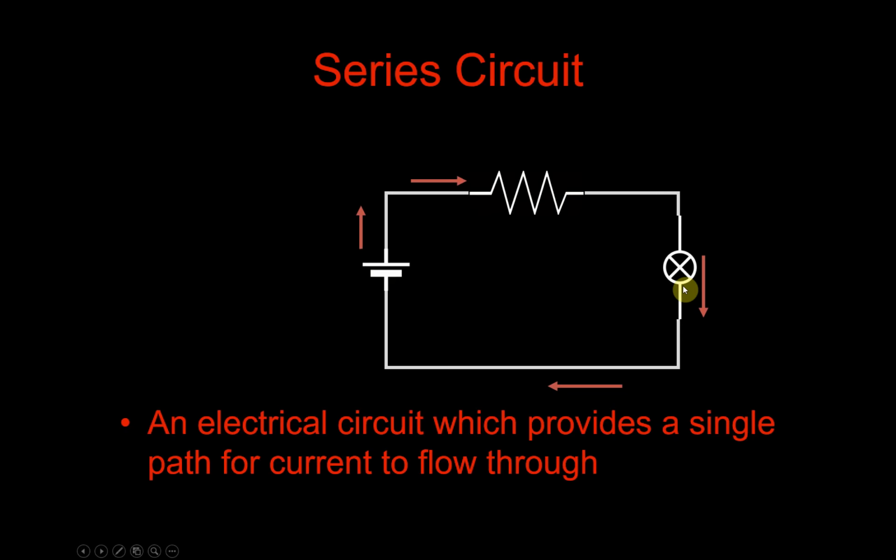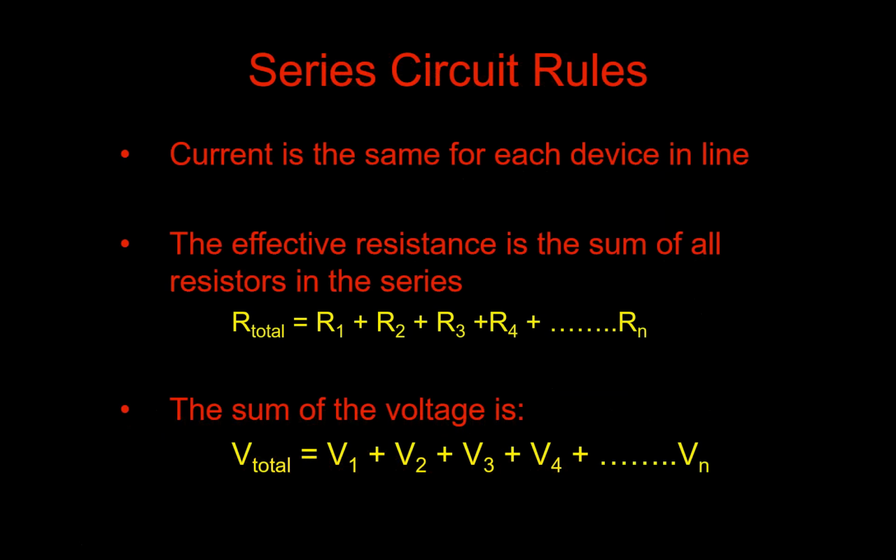So for our electrical system here, for our circuit, we have a single path for all our current to flow through. And you've seen similar rules for adding resistances as you have for adding capacitors, but the rules are flipped, so please don't mix them up. So if we're to find the total resistance of a series circuit, all we really have to do is add our resistances together.